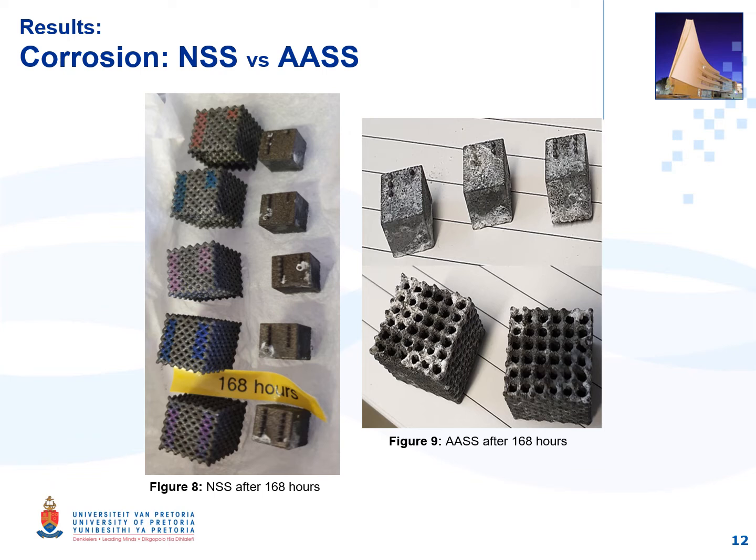After the defect analysis, corrosion testing was started. Figure 8 shows the samples after 7 days in the neutral salt spray, where some corrosion product has formed, but visually alone it cannot be said what the extent of corrosion is. Figure 9 shows the acetic acid salt spray samples after 7 days, where it is seen that more extensive corrosion product formed than with the neutral test.